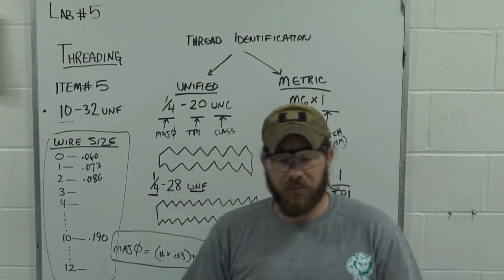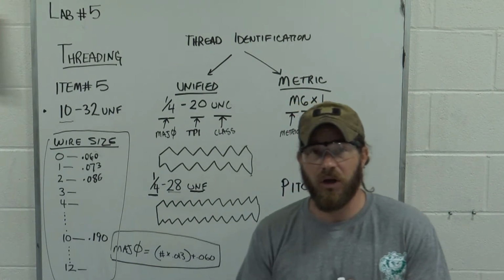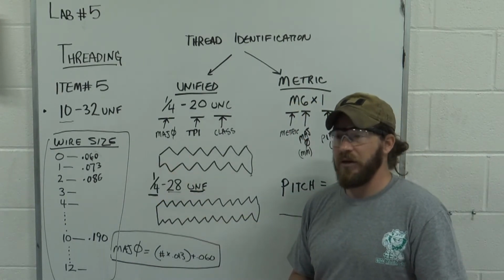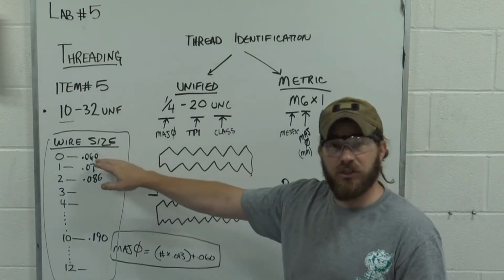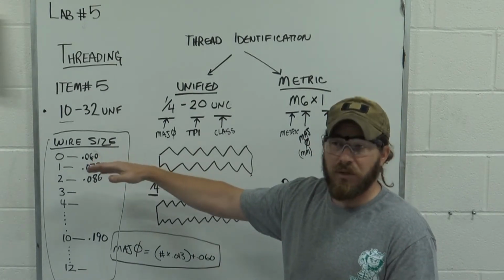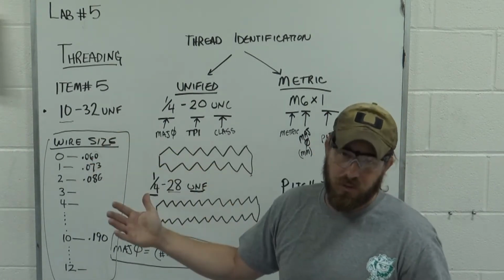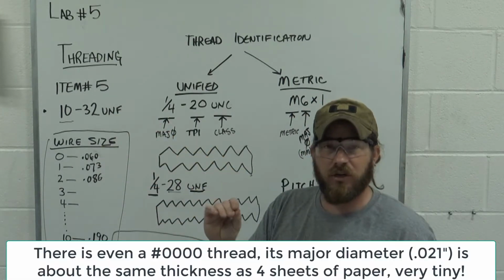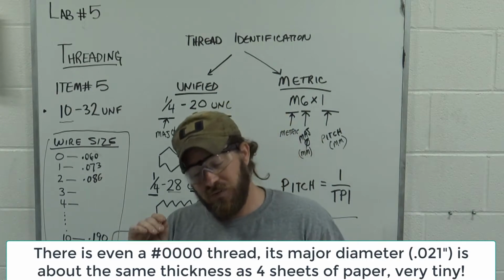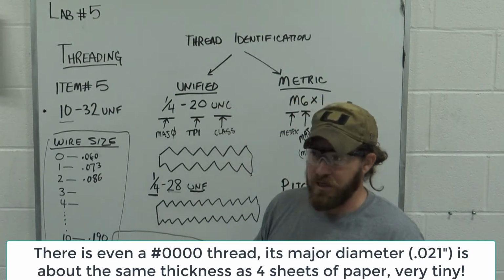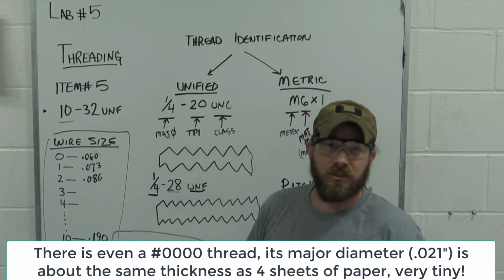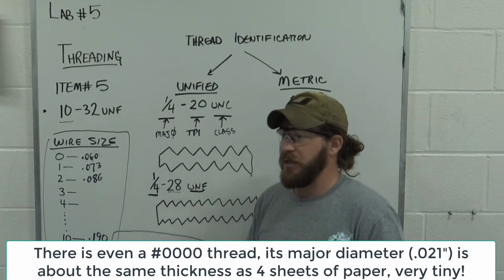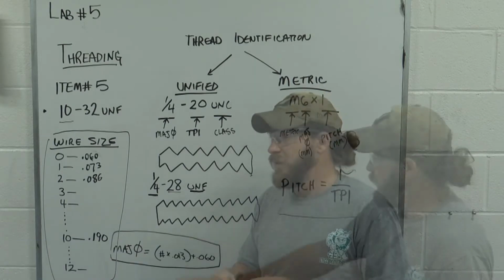Have that in the back of your mind, so when you're dealing with smaller hardware, you'll know how to size these out. They actually do make a 00, or double odd, and 000, or triple odd, and those are just minus those. But those are very, very small threads. You're talking like in some precision Swiss watches. So small that they practically make no sense to even make them.